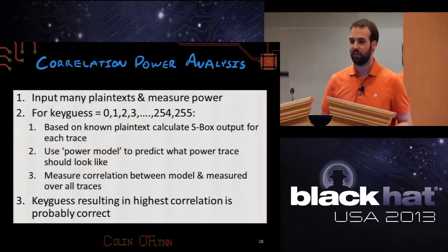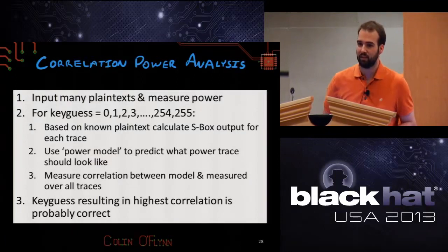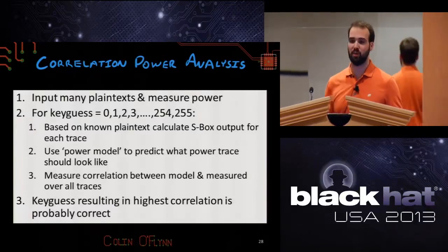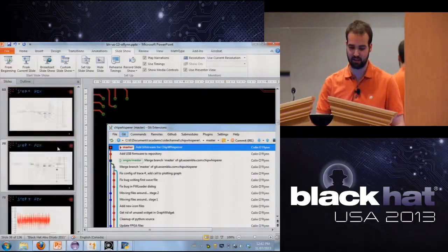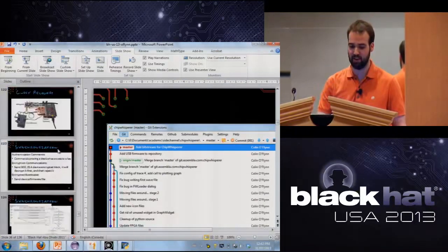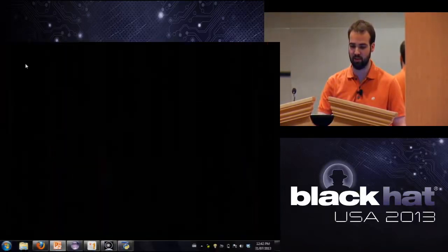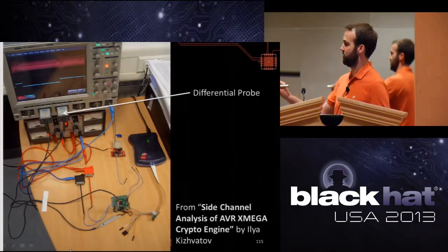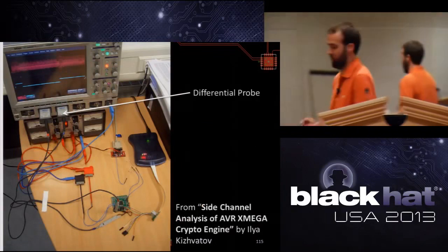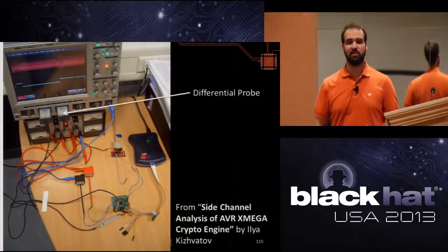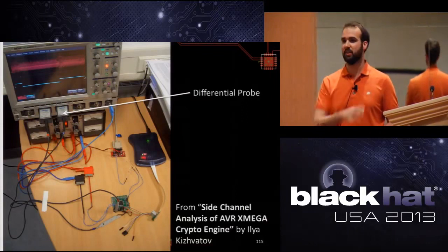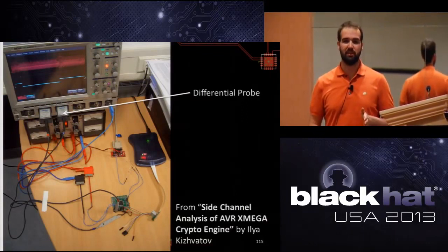What are your thoughts about attacking a device with the algorithms? I had a conversation a while back about a flash encryption that was completely not... I'm kind of curious about how one would be able to attack that. Yeah, so the question would be, because you can break hardware AES, it depends if they've tried to make it difficult or not. The example I gave before where someone's broken the XMega, the XMega is a microcontroller that has specifically a hardware AES core, so this paper here. This has AES done on the physical hardware chip itself, and they were able to break it. So just because it's in hardware doesn't mean it's uncrackable. For example, smart cards have hardware encryption as well, but they have countermeasures designed specifically to stop this, which isn't to say it's impossible. It's much more difficult now. So it would depend if they did that or not.